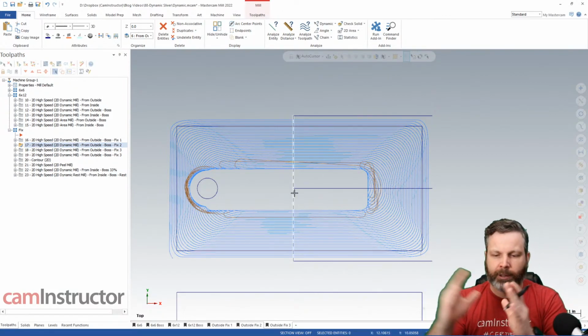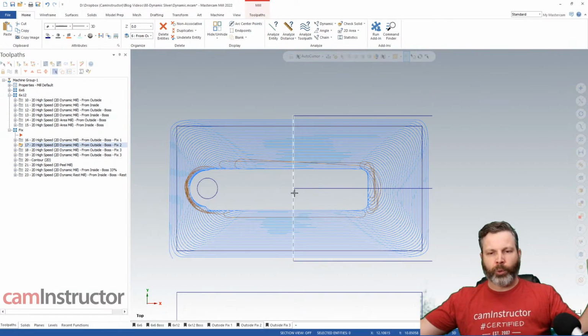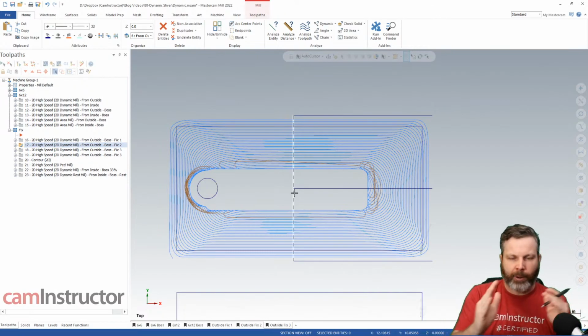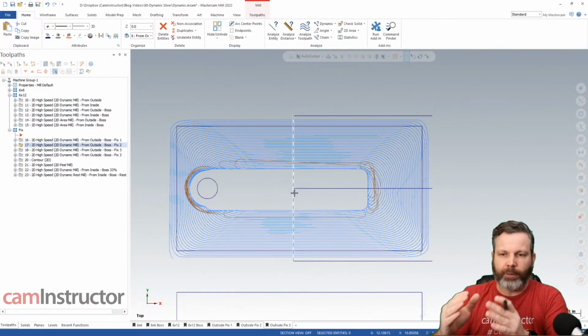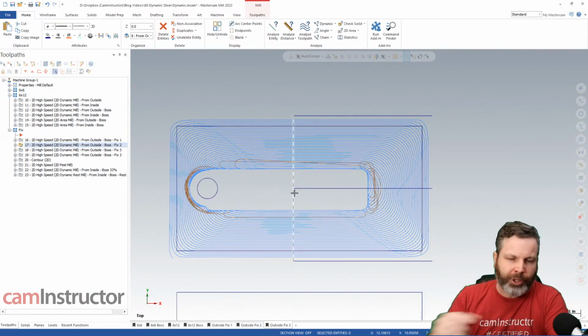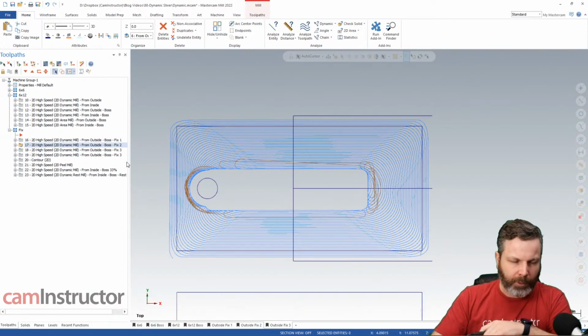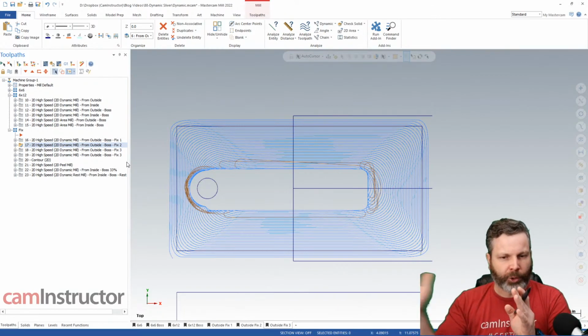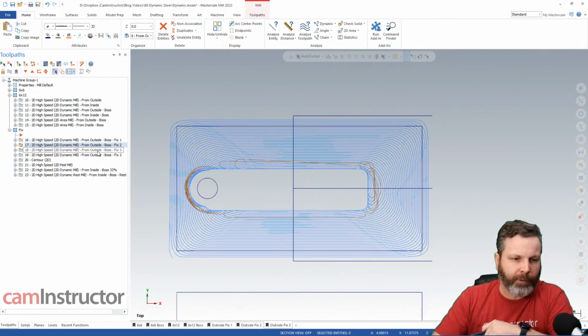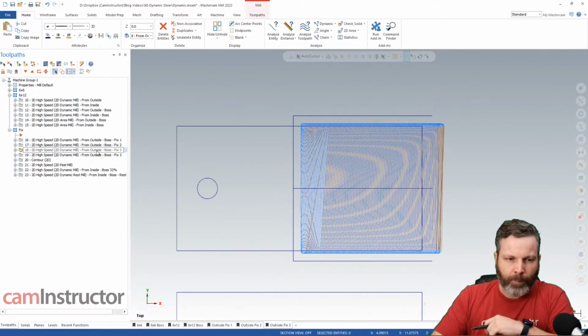So you don't need an exactly square part, but if your part is 20 inches long by 2 inches tall, if you can squish that 20 inches down somehow to maybe 6 inches long by 2, that will probably machine just fine. So we just need to look at different ways we can squish off that excess that's out of proportion in this toolpath.